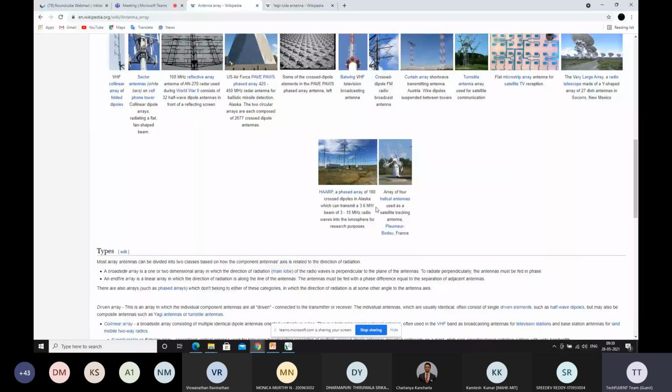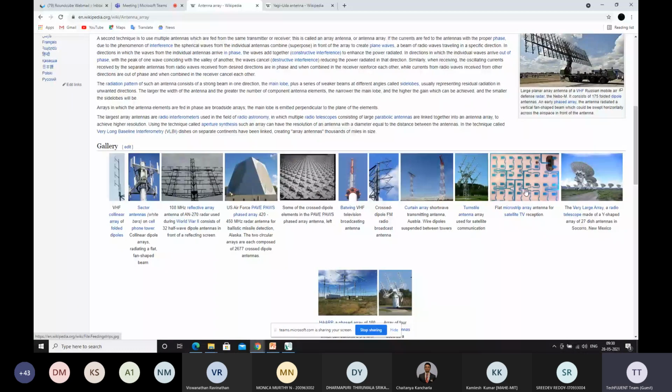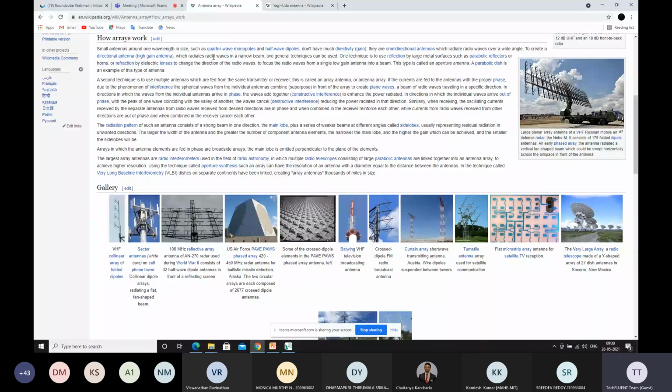We have different modes of antenna arrays, like in dipole especially we have end fire and broadside. How exactly this antenna array works is that you place all the half wavelength dipoles or quarter wavelength dipoles at a specific distance. This distance should also be equal to lambda by 2. Because of this lambda by 2 distance, the antenna will radiate until a specific point.